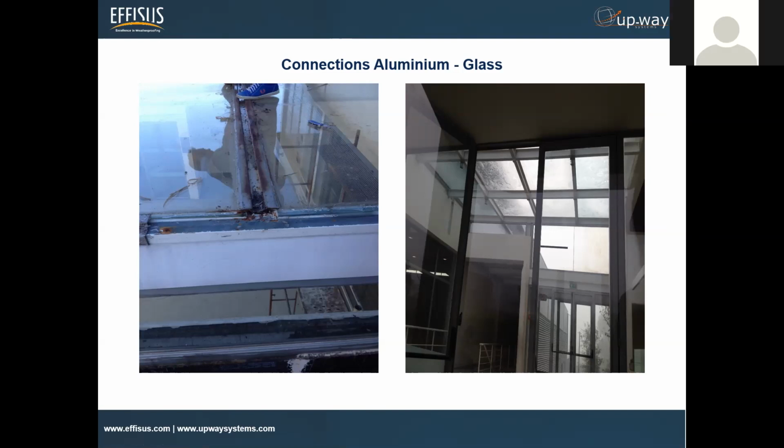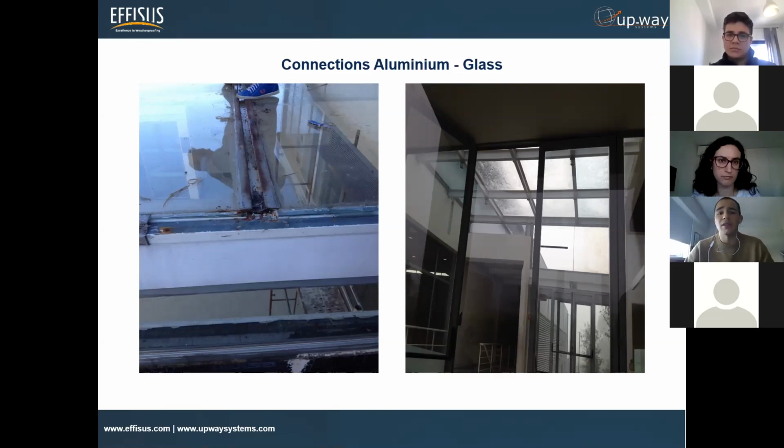most of the times because these things happen. We are putting these flashing details on the roof. These metallic structures are exposed to rain and to the sun, and they get a lot of corrosion. Most of the times, the solution that you will present today is used to rehabilitate this type of metallic structures. We normally put the membrane on top of this, and it's not only waterproofing, but it protects this metallic structure from the corrosion, and it's very interesting for rehabilitation.